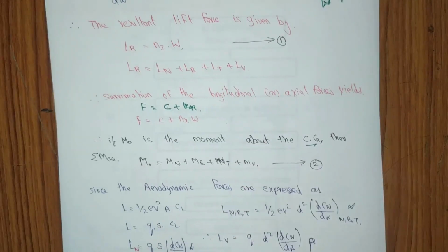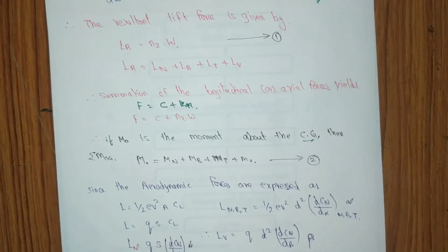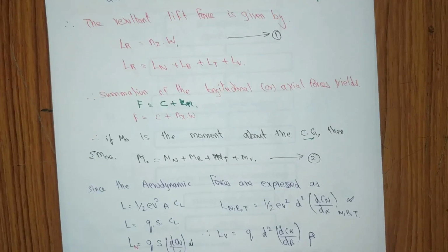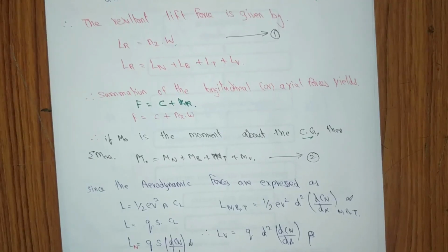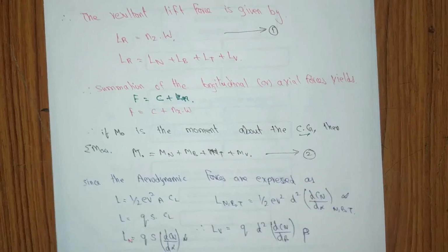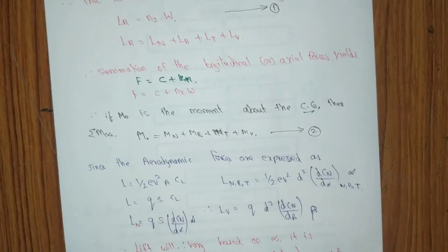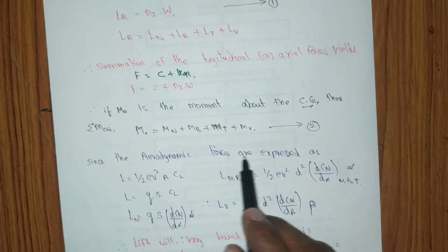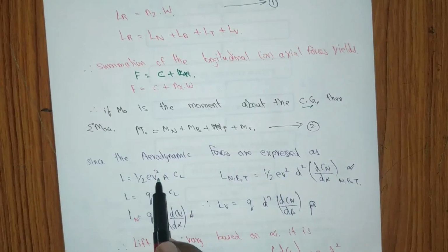Now we have to elaborate these lift forces as well as the moments to get a better, exact expression for the lift value, drag value and moment value, as well as what influences the angle of attack, alpha and beta. Beta is the angle of the controls. If the control surface is operated, how does it influence the missile in flying condition, right?